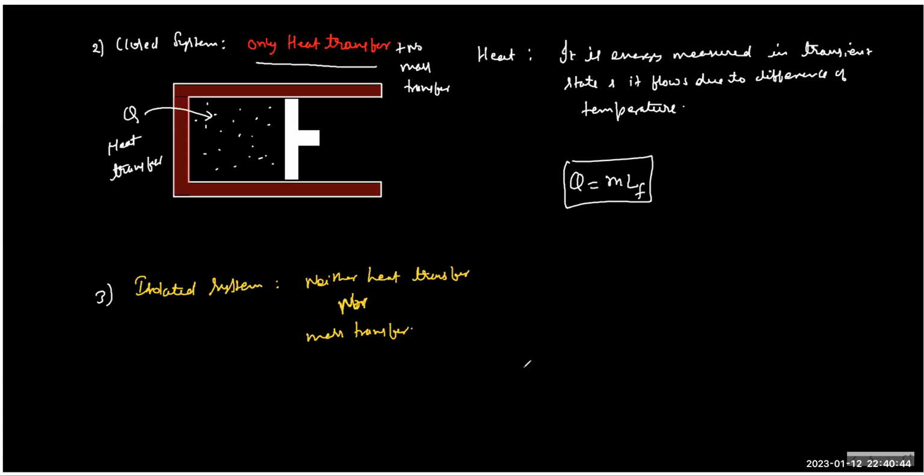So if I say that a process is isochoric, I hope you have heard in chemistry, at least in thermodynamics. A process is isochoric. What does it mean? Sir, no work. Volume remains constant, sir. Which means I will say the boundary is fixed. So if the boundary is fixed, which kind of transfer will not take place? Work. Yeah. So in an isochoric process, there is no concept of work transfer. So the relationship between the heat given and internal energy change is the only relation possible for such a process, isn't it? Yes, sir. So we'll see the process very soon. Anyway, this part is clear.